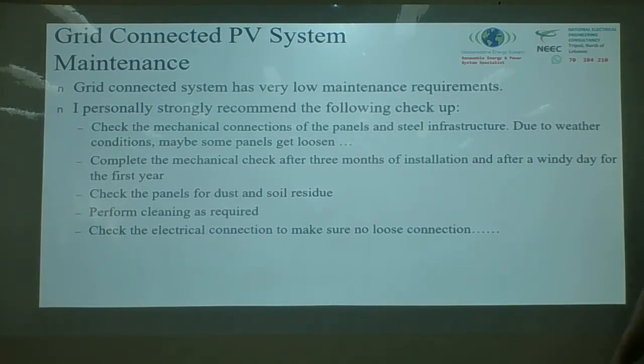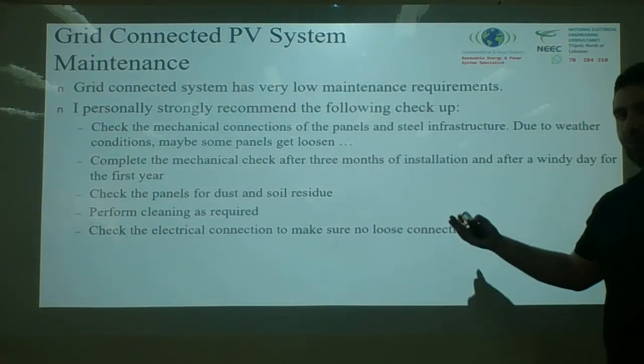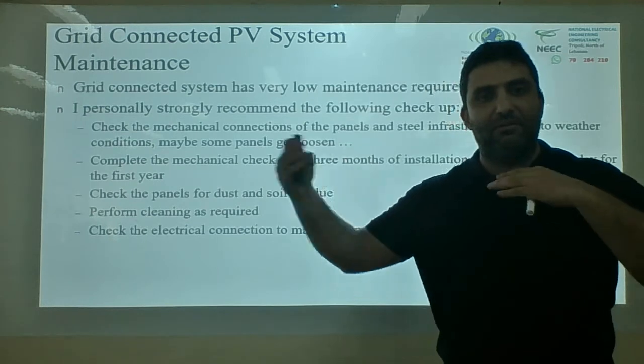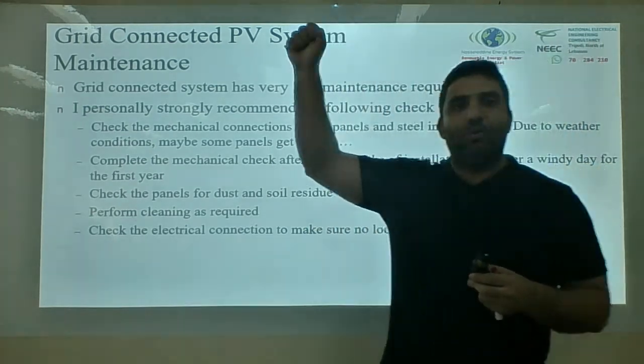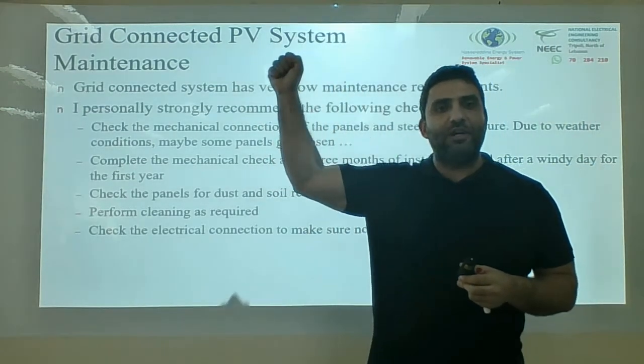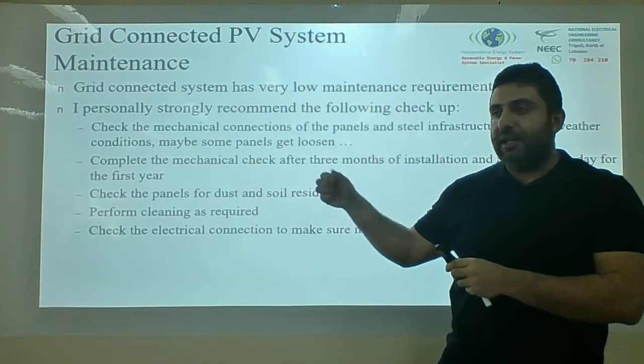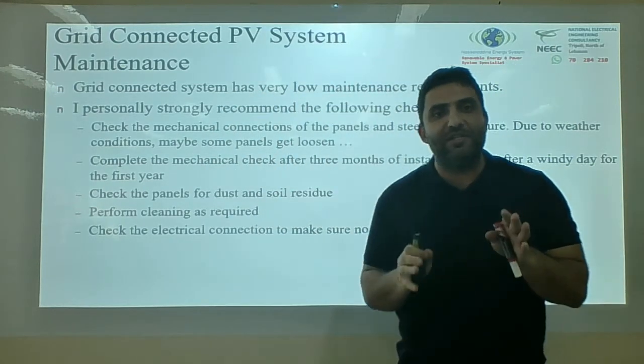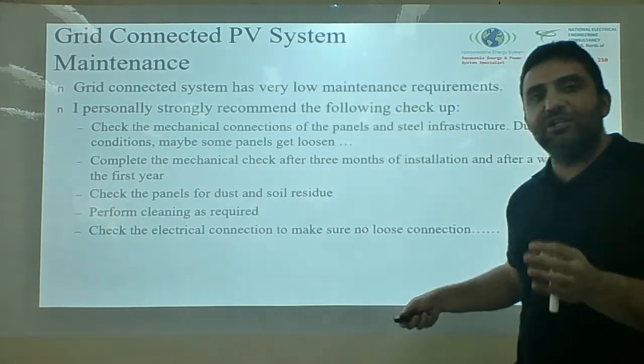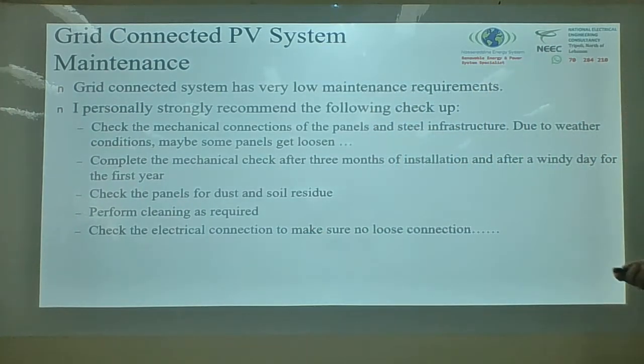Check the electrical connections. I recommend you, after a while, because there's a lot of wind, check your cables. Number one, is my cable still solidly connected? Are all the cable ties still properly done? Is there any loose connection? I check all the stuff in case I forgot about it, especially during the first year, during the first storm.